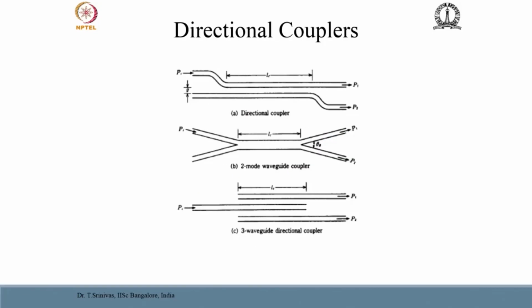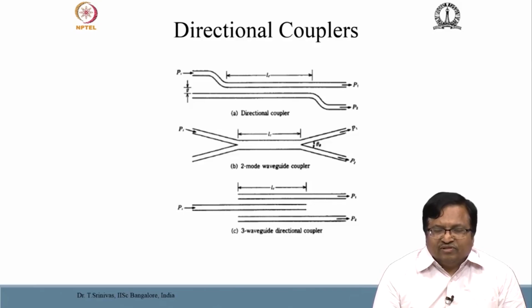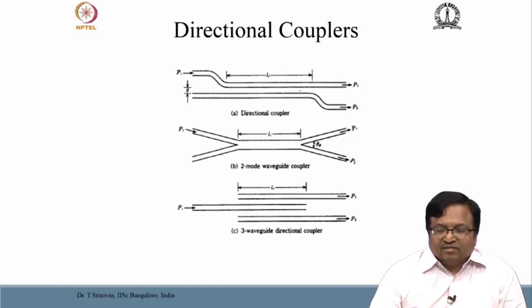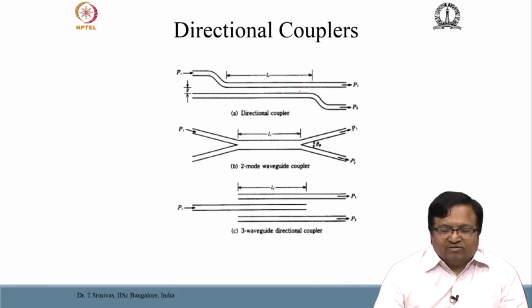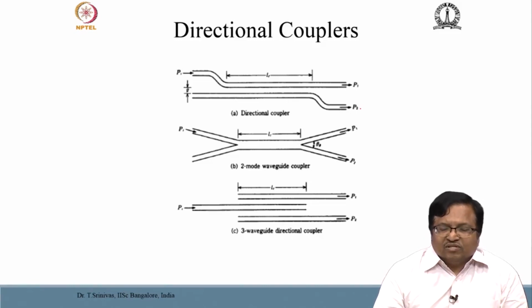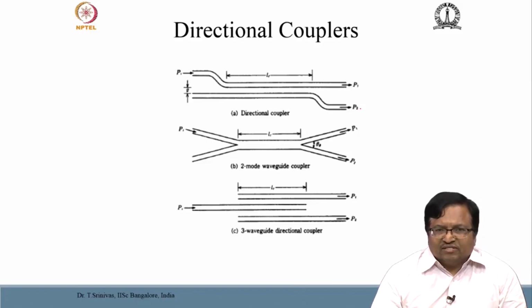In the beginning we have seen a directional coupler where light could be exchanged from the input port to any of the output ports, with a higher refractive index region in the waveguides and a lower refractive index region in the intervening medium. So, we saw that the light could be tunneled from the input port to the opposite port. Directional couplers are very useful for many applications, for switching the power between different ports or redistribution and so on. A directional coupler is typically considered a multi-purpose device which can be configured for many purposes, in particular in association with other electro-optic effects.